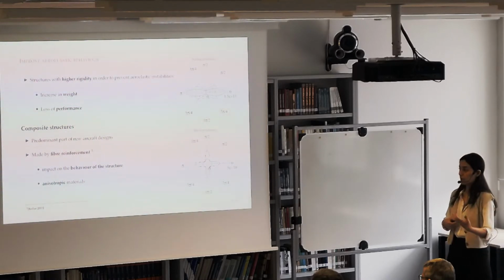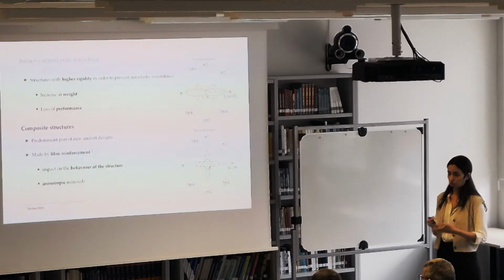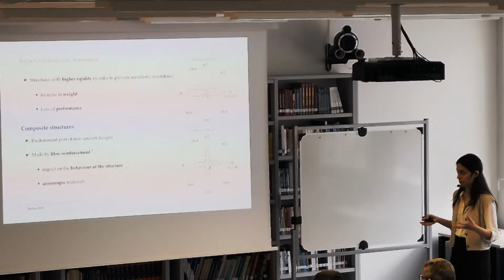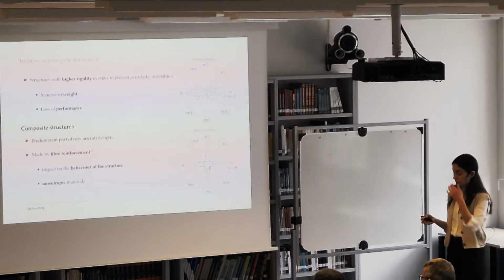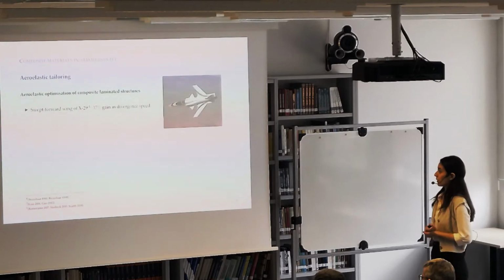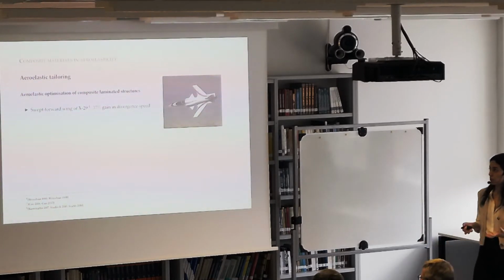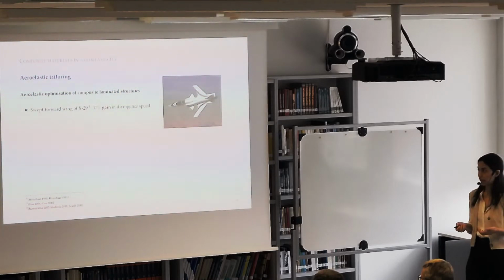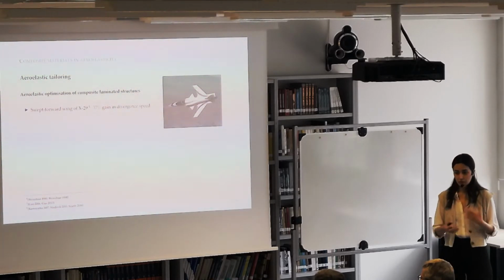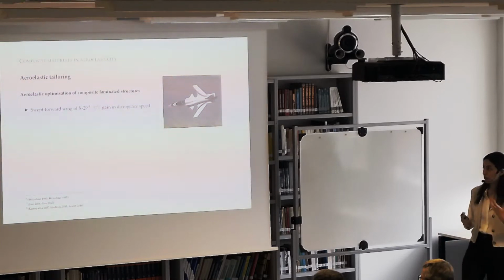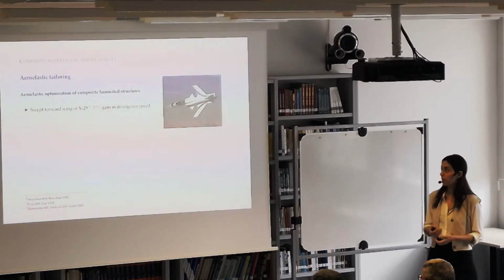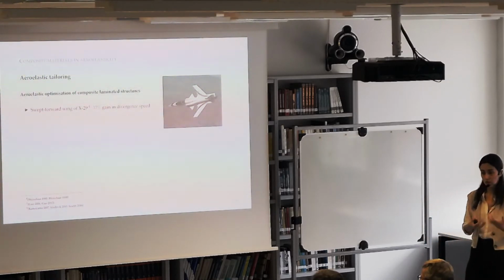Of symmetry, but it will also have laminates with elastic symmetry and anisotropic properties. The use of composite materials in aeroelasticity gives place to a domain called aeroelastic tailoring. In aeroelastic tailoring, we try to improve the aeroelastic response of our system by modifying the properties of a composite material.